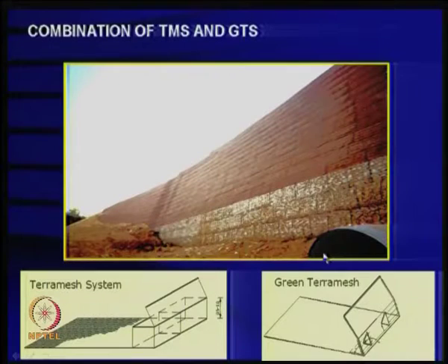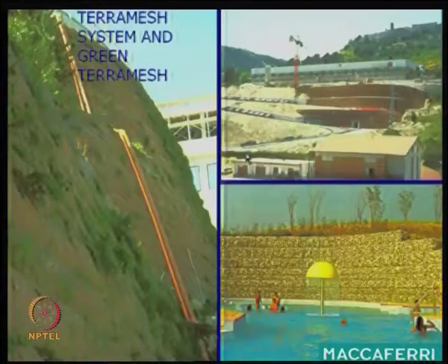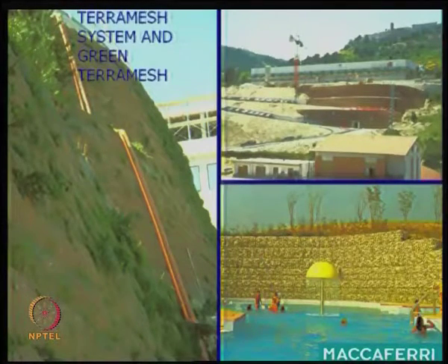In fact, what I saw in the particular RE wall, RE slope in the other place called Vijayawada, was that they could not estimate the deformations of the slopes properly. That was a big issue. Now it is somewhat stable, but it has really been a problem in reinforced soil slopes, because the height is 42 meters, which is not a small height, and it is also on a curvature. There are many design issues, and this is another example that one can have here.